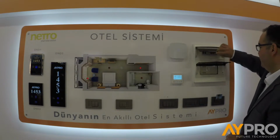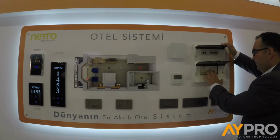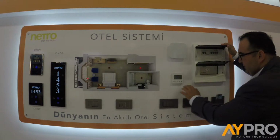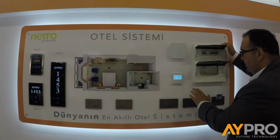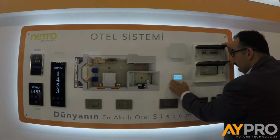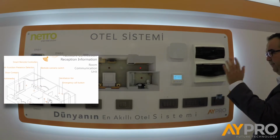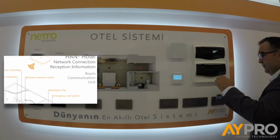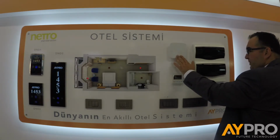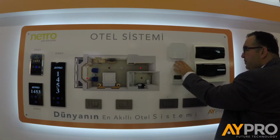And for the panel distribution board, you have standard fuses here, and you can use any brand, and you just use our hotel integrated system, and this can be connected to the thermostat directly. So in one room, we have one room controller on the panel, and you have one thermostat here. And the communication is very easy, because we don't need any Cat5 cables or any bus cables through the hotel room. We just have the gateway here, and the gateway stays in the corridor, and this gateway can talk with 10 up to 15 different rooms.